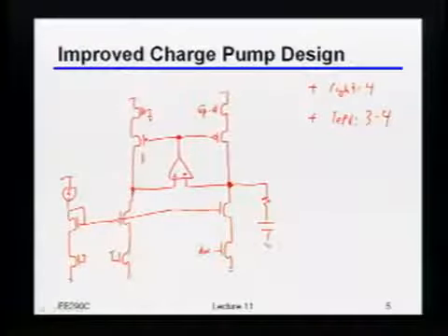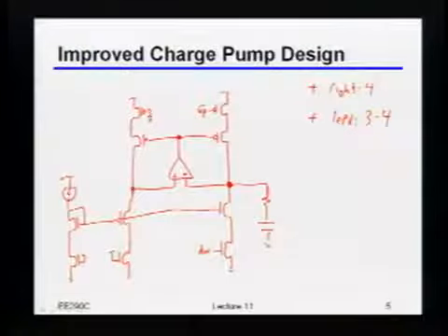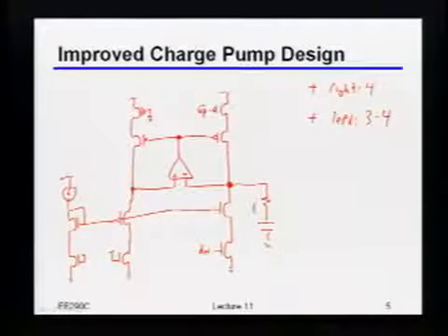But then ideally the control voltage is sort of DC, right? So why do you need so much bandwidth? Well, it's true that this is sort of DC, except that it's not really DC, because the loop has a finite bandwidth associated with it. So if your loop has 20, 30 megahertz of bandwidth, then roughly speaking, this also has 20, 30 megahertz of bandwidth. Not exactly, but roughly speaking. Does that make sense to people?